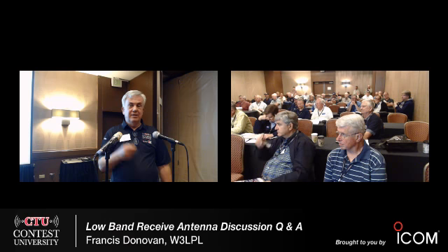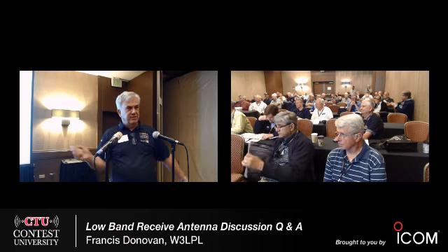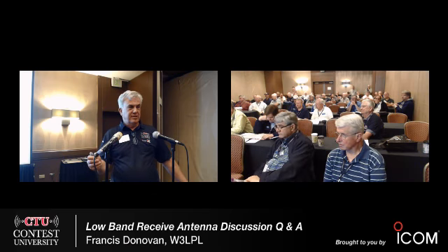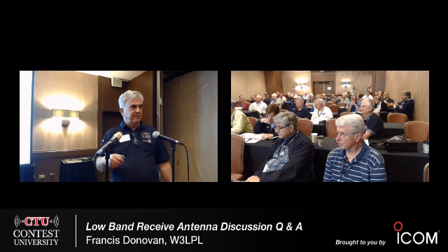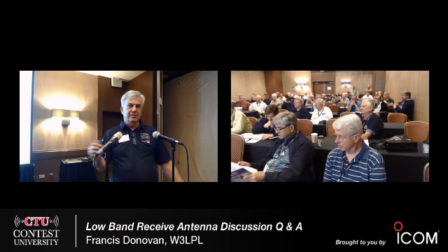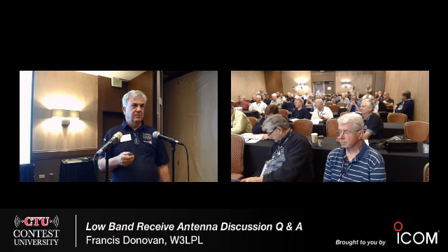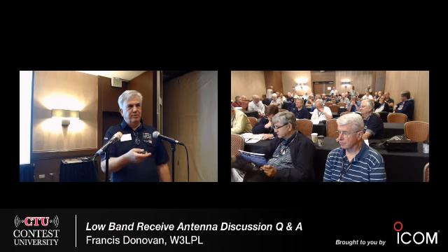Yeah, that's a problem. It's a very clear advantage of the low impedance antennas that they are immune to this. There's no active component in the low impedance version of this antenna. It has the disadvantage of having radials, but it has the clear advantage of no active component, so it has no susceptibility at all to nearby strong signals. So if that's a real serious problem, you might think about a low impedance version rather than the high impedance one. Any other questions? Right here.